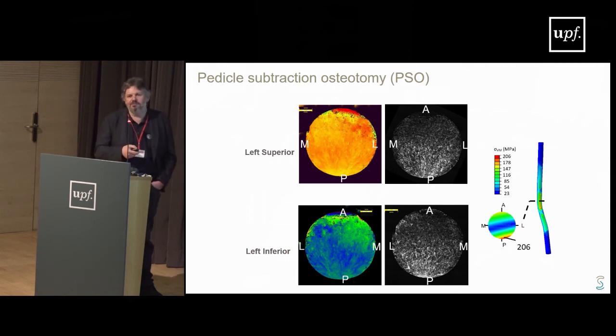If you know something about fracture mechanics, you will recognize that it's a typical fatigue fracture, starting from here. Then here we have the propagation, and here we have the rough surface that indicates the final rapid fracture. And it's very interesting to note that the fracture started in the posterior position, which is exactly where we predicted that we have the maximal stress. So that's also another way of validating the model once more.